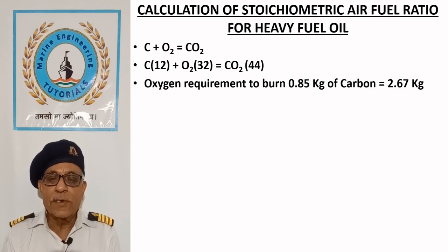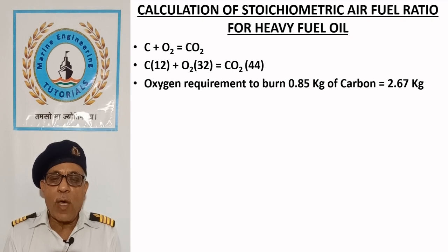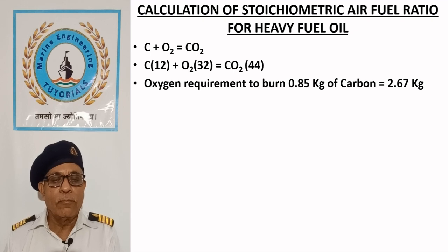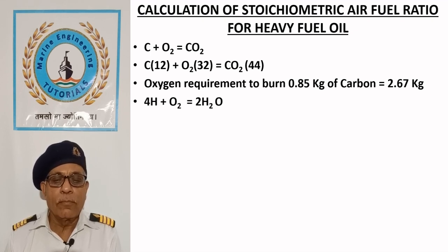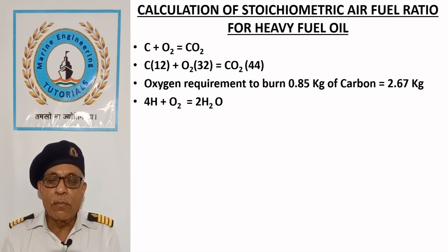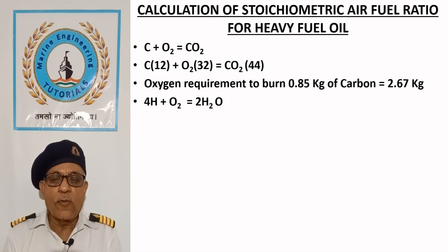As carbon percentage in the fuel is 85%, oxygen requirement for burning 0.85 kg of carbon can be worked out as 2.67 kg. Four atoms of hydrogen burn with one molecule of oxygen and form two molecules of water vapor.